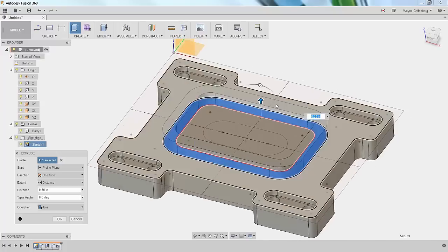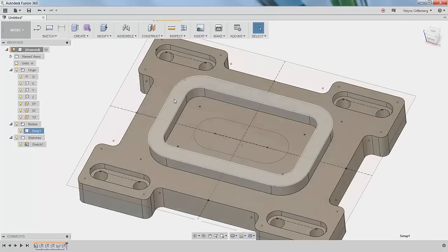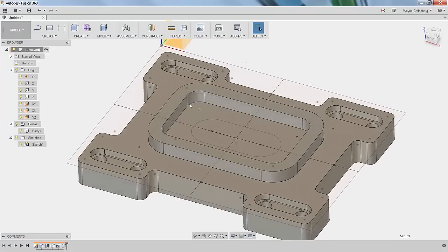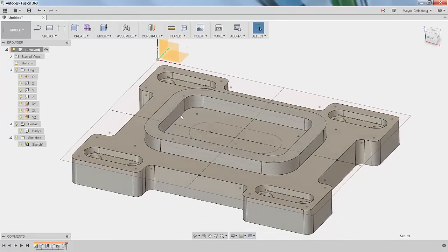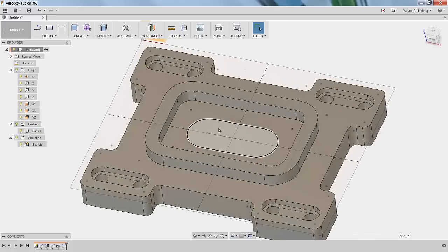I can also do it with Modify. But here I'm going to extrude it up 1/4 inch. Now we have a boss on top. And now what I want to do is I want to have a loft. I want to have that venturi go down to the bottom of the part, and on the bottom of the part I want this feature.